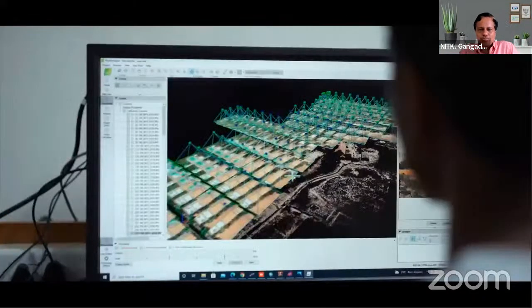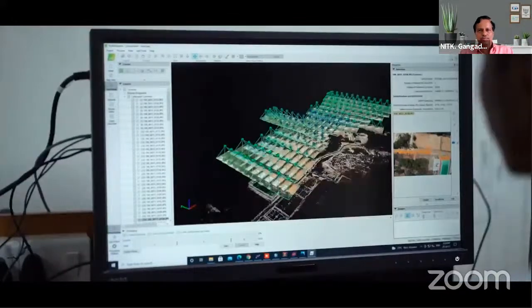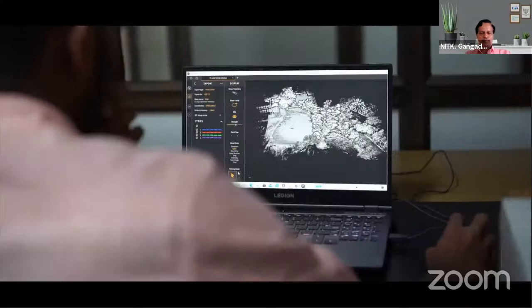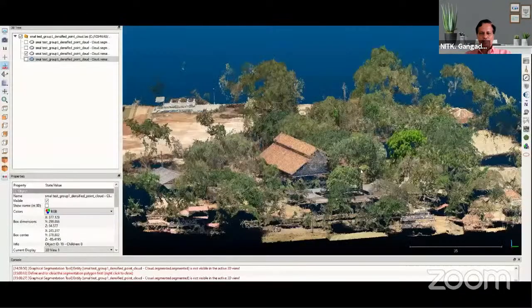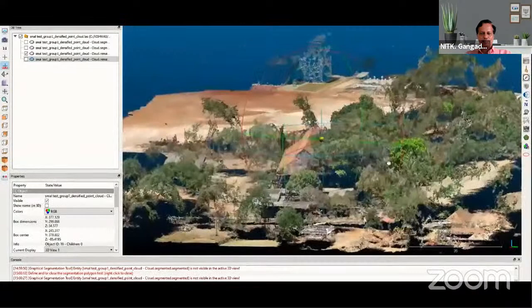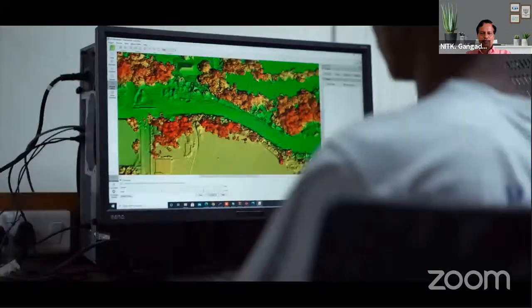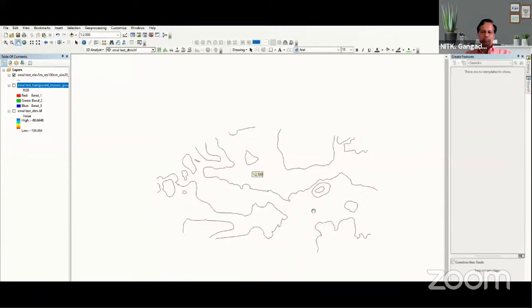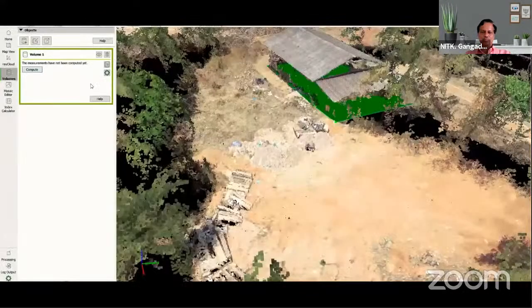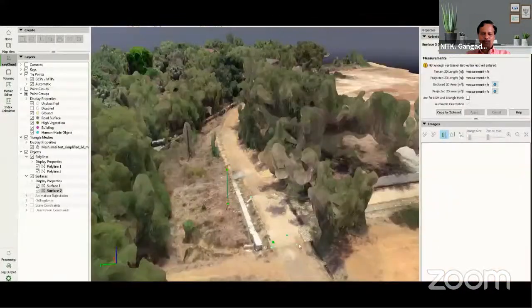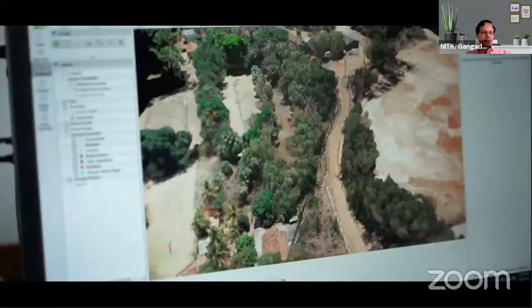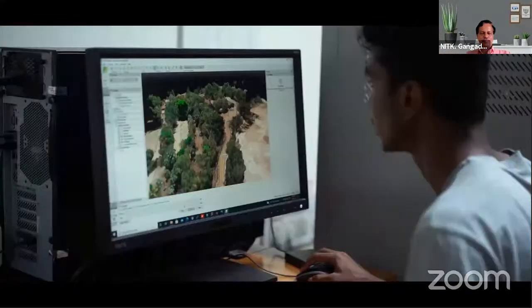The images captured through photogrammetry are stitched together, analyzed, and the processed data is merged with the LIDAR data so as to get a highly accurate data set with RGB colors. From this we can get the orthomosaic map, DTM, DSM elevation model from which we can obtain detailed measurements of any point in the area such as cutting and filling, area calculations, volume estimation, etc. And this data can also be used for creating 3D mapping and printing.